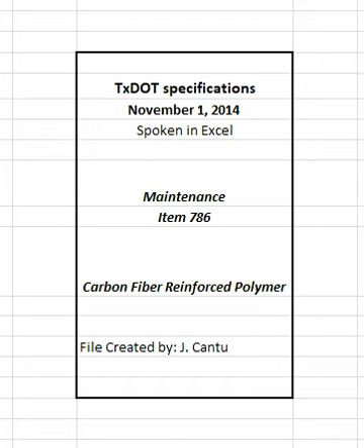Identify the environmental and substrate conditions that may affect the application and curing of the CFRP system. Calculations must show the proposed system provides the required strengthening as designated on the plans.